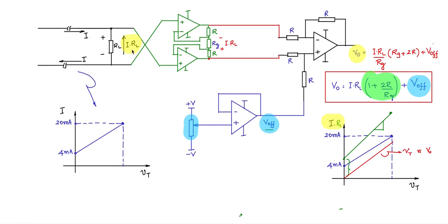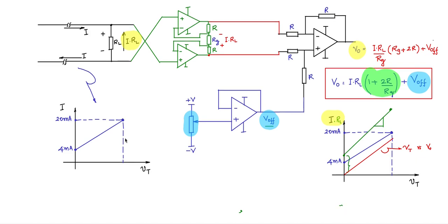So this way you will see the entire block of circuits from the sensor to the A to D. If you take from the sensor point, from the sensor transducer, the transducer output voltage or current is converted to a compatible voltage range using zero and span circuits.